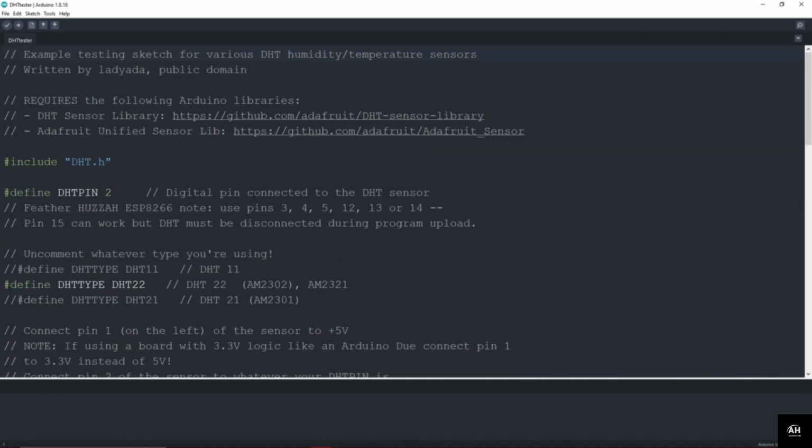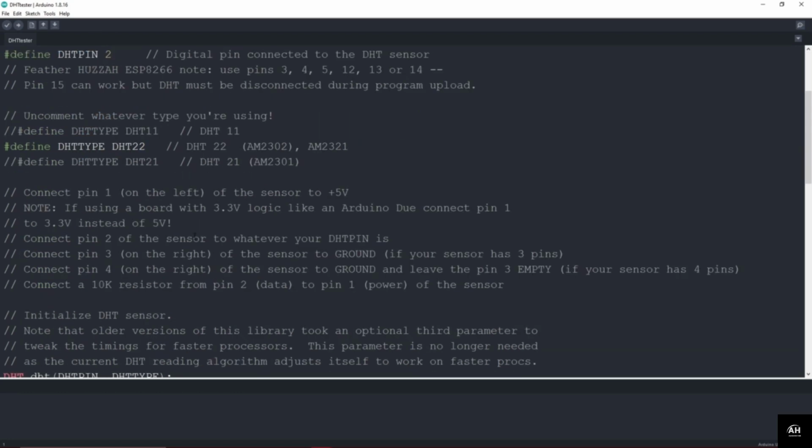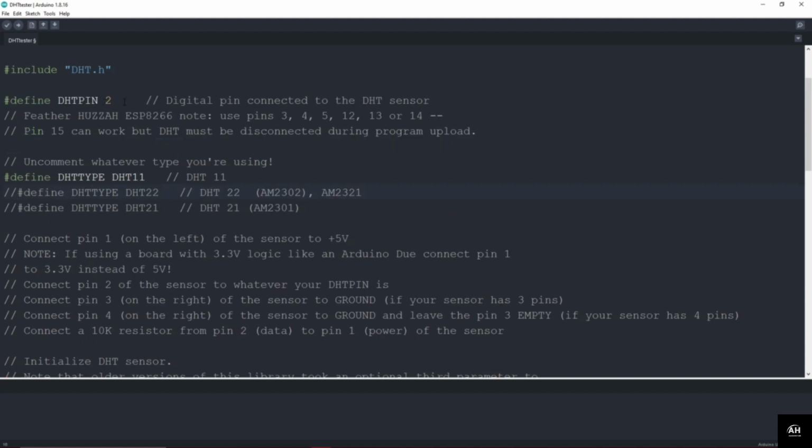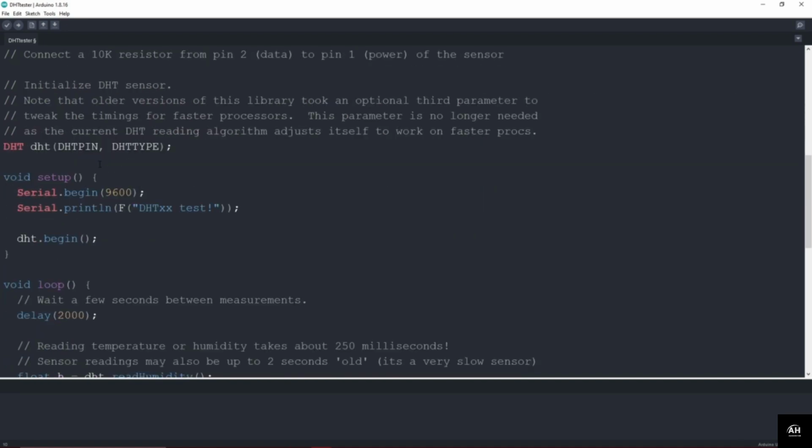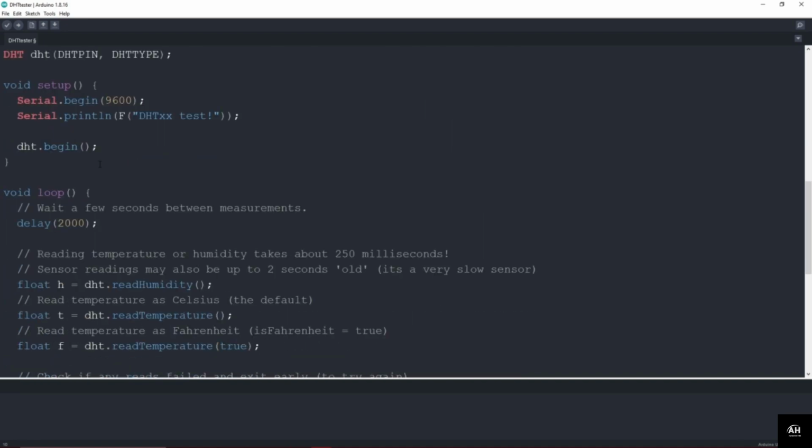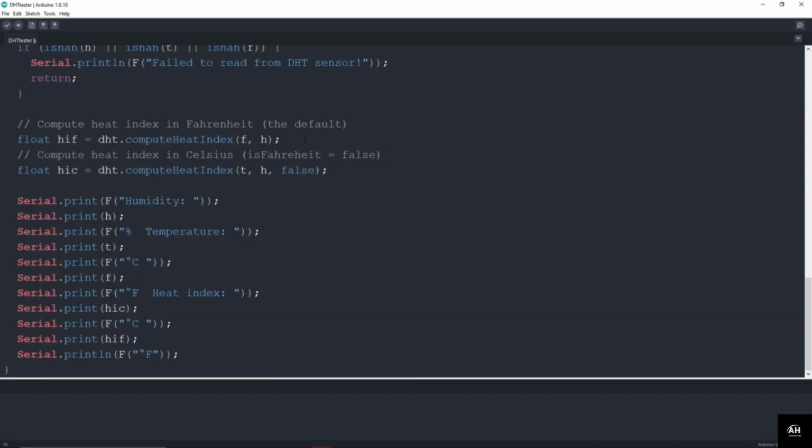you can see here are some pins that are defined here, and we are using our DHT11 sensor. So you can see here is some DHT22. So I will just uncomment this part which is for DHT11. I will just comment out the part here for the DHT22, and we have connected our DHT sensor with the pin 2 previously. So here is the digital pin 2 which is defined for the DHT sensor, and if we scroll down, you will be able to see the entire code. So this is the entire code for checking the temperature with the help of the DHT11 sensor.